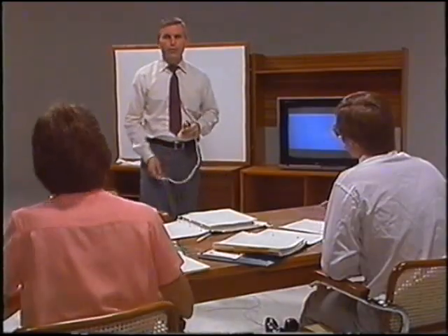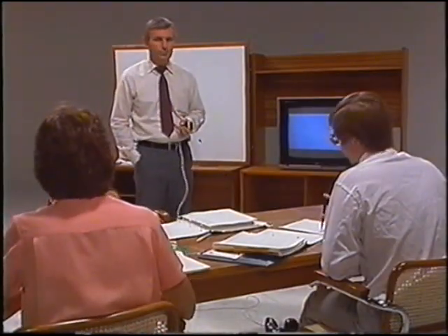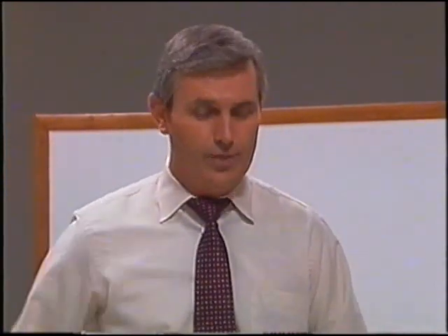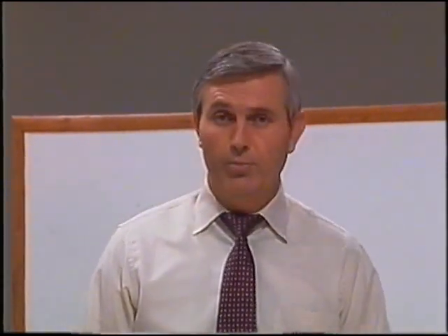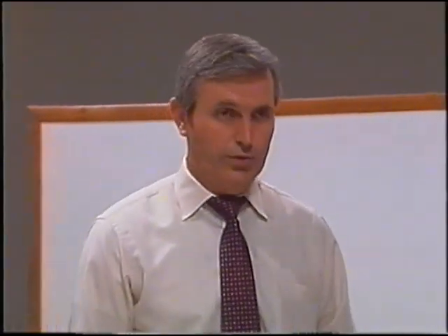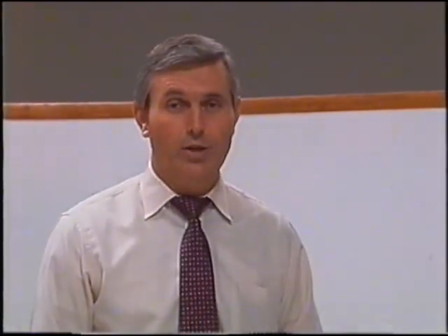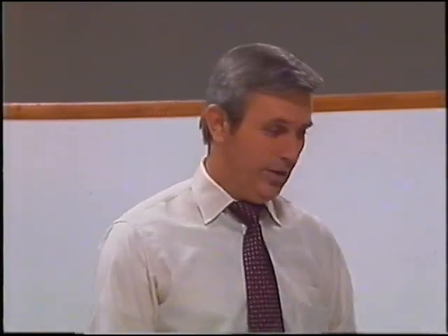What do you say about the likelihood of fingers forming in a slim tube? Myra? I would say that's fairly small. Your critical wavelength is 2 centimeters, and I think that in the slim tube experiments, the maximum was less than 2 centimeters. Yeah, the biggest one was 2 centimeters. Most of them were of the order of half a centimeter. In fact, the lateral extent on a slim tube is, by design, fixed so that the fingers can't form. That's why it is that way. Here's another reason for saying that slim tubes give you arbitrary or artificial displacement results, because it has been designed to suppress an important phenomenon, namely viscous fingering.